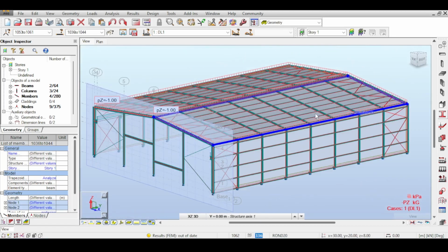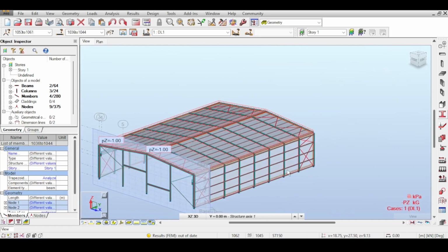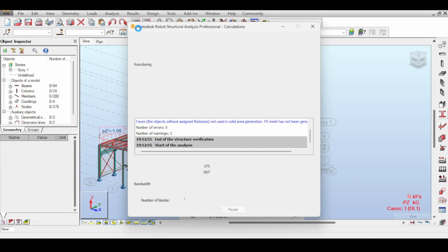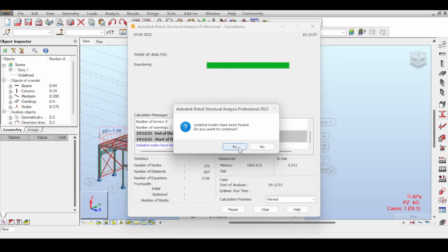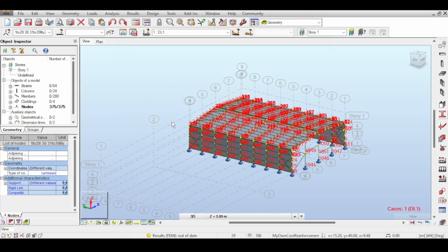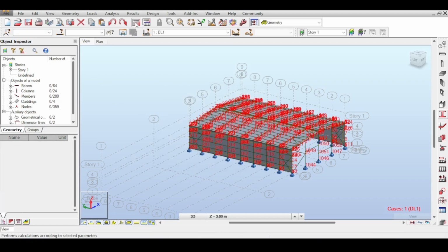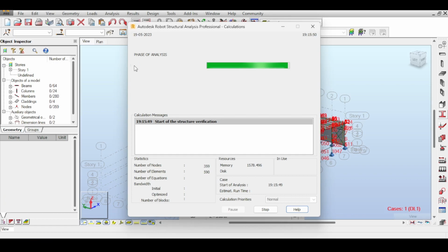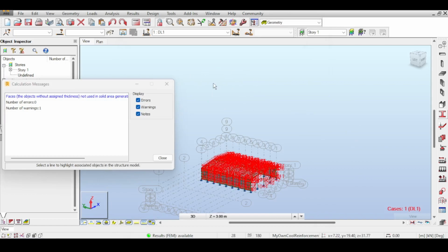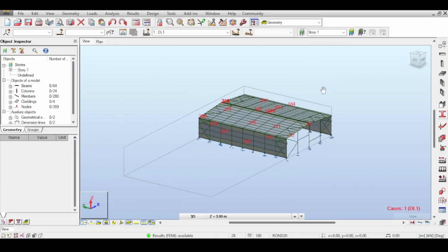I have an idea, and this is some unhinged thinking. Follow me with this. So what I'm going to do is run the analysis first, just to make sure things work. And things do work. Isolated node. Okay, that's not a thing I wanted to see. I have an idea. Select here, all, enter, and then delete. Delete only selected members. Okay, run the analysis now. It should fix the problem. It does. I think that happened when I edited and moved it up. I think upwards they were the nodes. So, okay, I've just finished the isolated node problem.